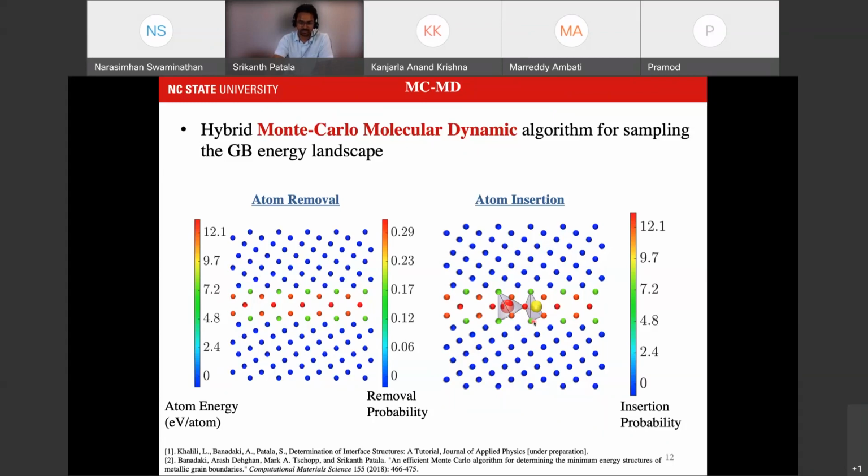And I think that's where I see more of a utility of using these descriptors to estimate not just the energy, but let's say mobility or some other property of a grain boundary. We did try to estimate which positions to insert atoms in using some of the SOAP descriptors, and finally what we realized is the volume of this tetrahedron, or the Voronoi volume, is a good enough descriptor for inserting atoms. So really, the answer to your question is, what are you trying to do?